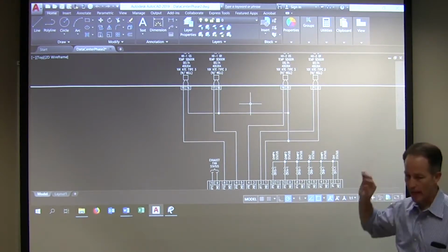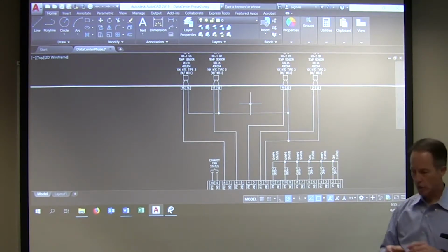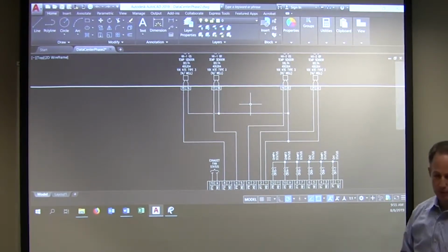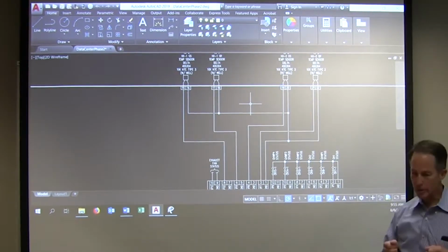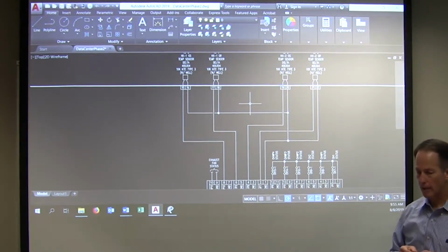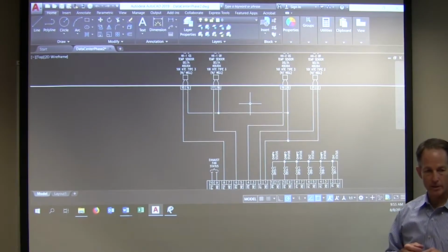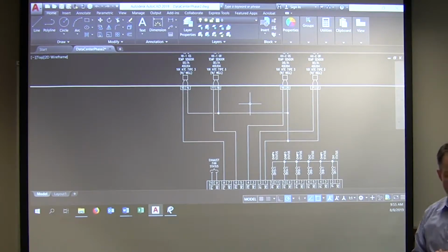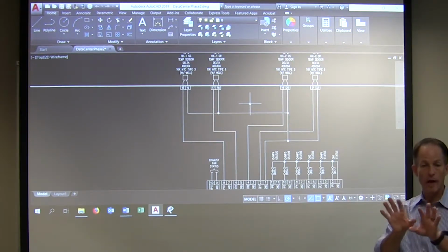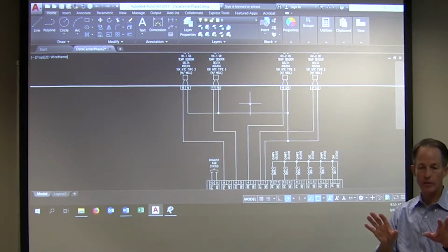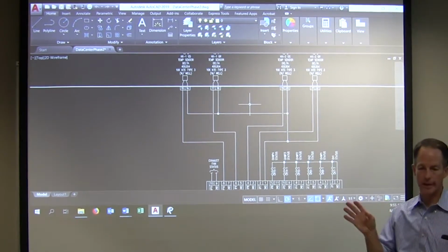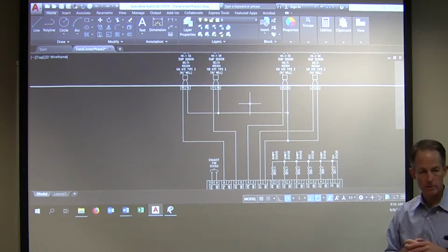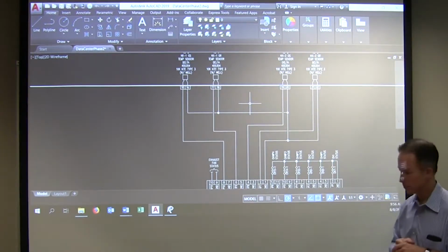So say I've checked that and everything seemed to be good. Sensor doesn't go to ground anywhere. I'm reading my 21 something on the resistance for a 45-degree pipe. What do I do next? I'm still having trouble. So on the graphic, it's either not reading, or it's totally zero, or it's not reading correctly. Then you hook it back up and go down to your board, and check your wires.